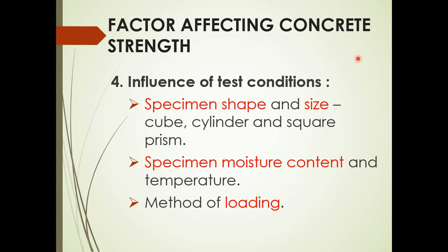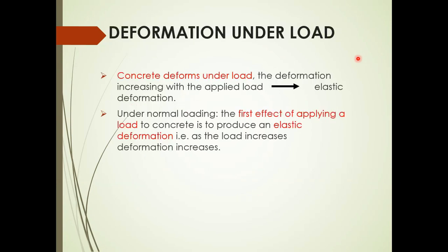Okay, so the fourth factor that affects our strength is the test condition, which depends much on the specimen or the size of the testing specimen, and also the specimen moisture content and temperature during the testing, and also the method by which we load the testing specimen. Okay.